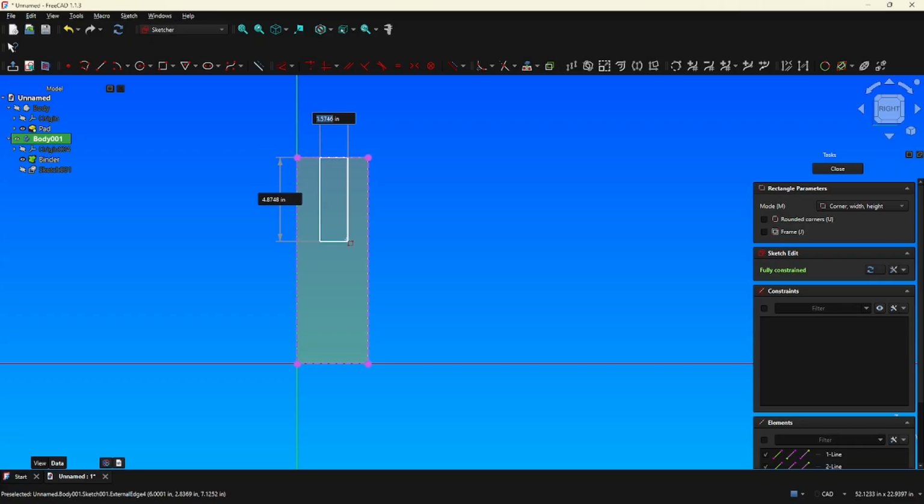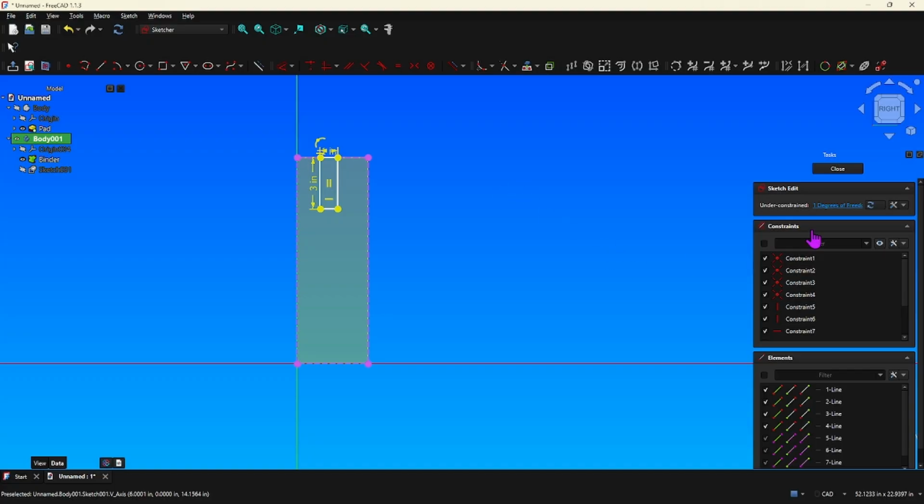All right, so you can see that coincident symbol is there on that line. I'll select, and I believe he had it as a 1 inch, select enter, and a 3. I think he did a 1x3. All right, right click to get out of that. All right, we got 1 degree of freedom. We have the 4 inches. We have the 3 inches identified, and those are the constraints for the rectangle. The other constraint is this coincident to this line here. So now that's just going to slide left and right.